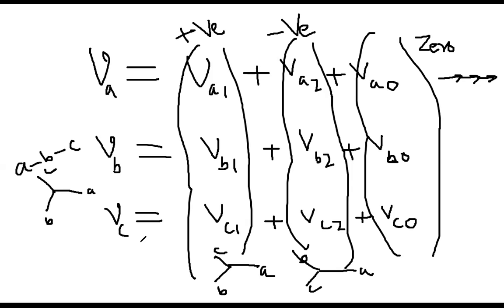So therefore, everybody, once again, originally at the leftmost side, I had a three-phase unbalanced system, VA, VB, VC, that has the phase sequence ABC. Because this is an unbalanced system, with the help of symmetrical components we decomposed each phase into three parts. Each set has created a balanced three-phase system, but they have different sequences. Like this set with 1, 1, 1, ABC.